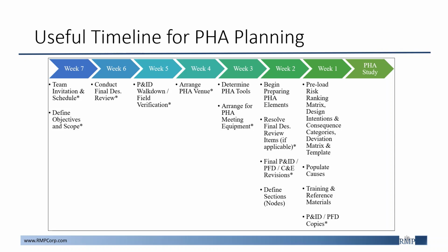This final week should also be spent populating causes so that the facilitator can look through the system and locate as many hazards as possible so that they may begin the system with any questions that the team members can answer. This reduces the time spent searching for causes and ultimately getting more out of the time spent with the highly experienced team members. Since the facilitators are well experienced with the HAZOP methodology, this pre-causing can be effectively done prior to the study date and can help newer team members understand the HAZOP methodology.